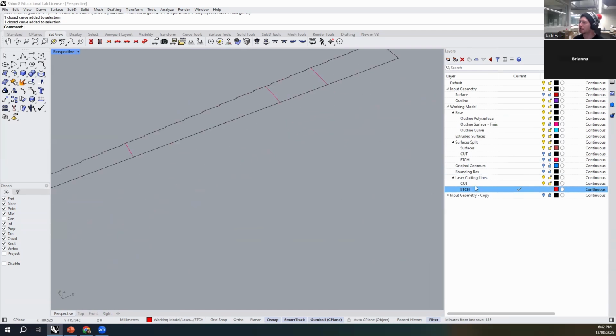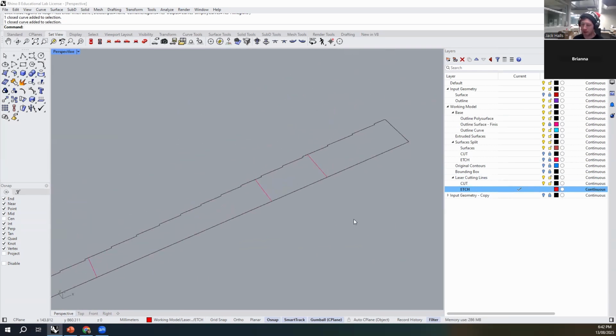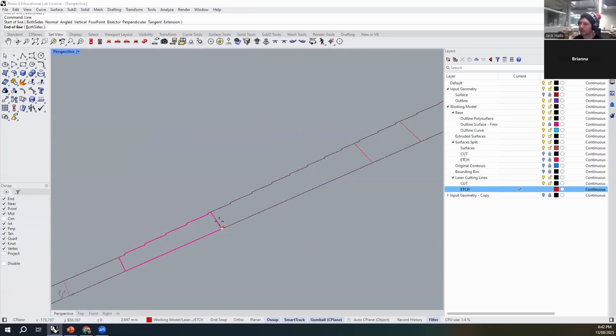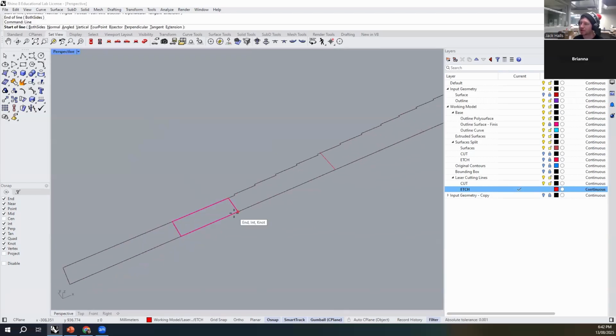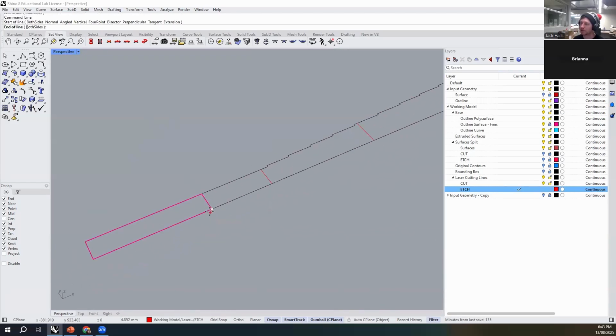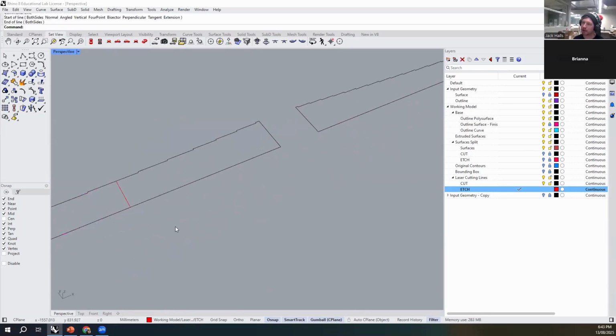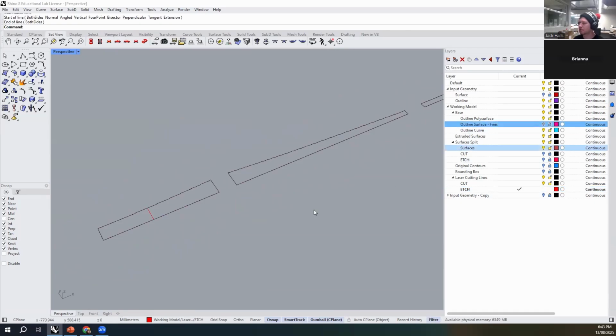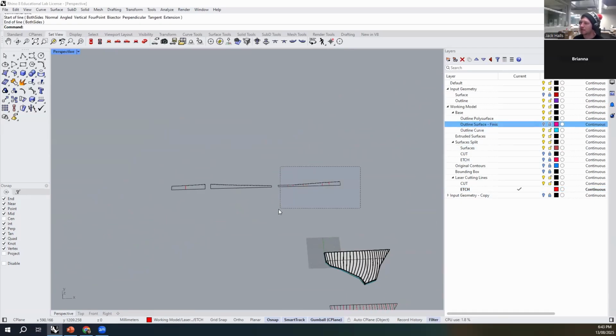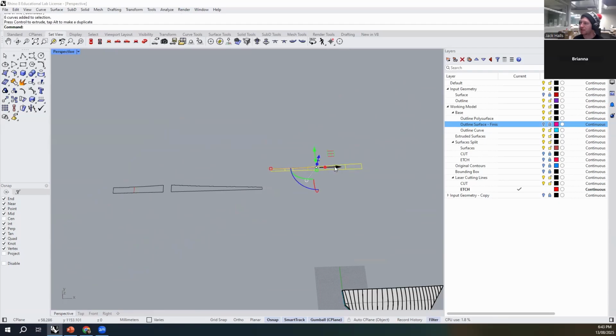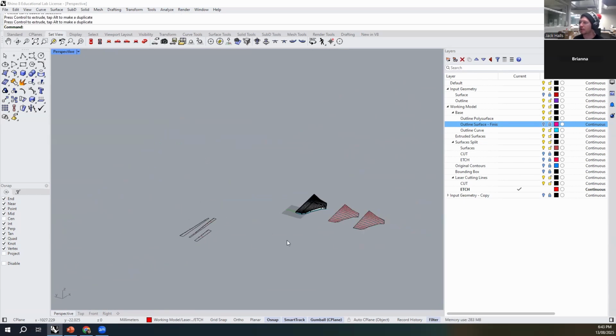And I'm just going to use etch layer. I'm going to turn that on. And I'm just going to use a line command really quickly. I'm going to withdraw those. So what that'll do is it will just etch that line into the material for us so we can see where to follow. Just to make sure that we're aligned. Okay, so those components, that's our optics card edge strip. That's great. We've got all that sorted out. And we'll add that to our next second. Leave that over there for a minute.